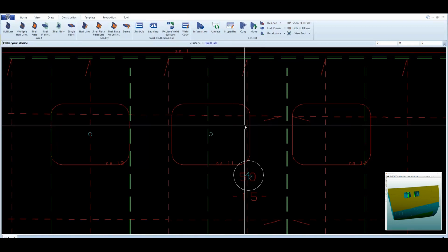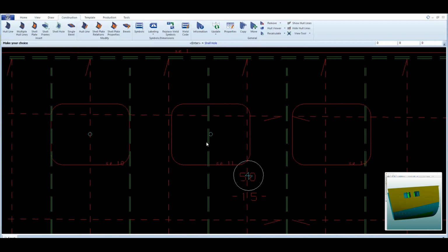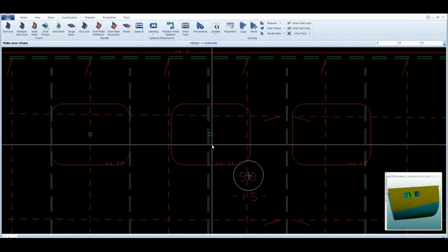If you remember, for the seams that we have created here we used the maximum property. This maximum projection property is a special projection property made with dedication for holes, because as you remember, it is a combination of the inside and outside projection. The inside projection refers to projection on the inner shell plate surface, that is opposite to the shell plate normal, and the outside projection refers to projection on the outer shell plate surface, that is parallel to the shell plate normal. The result is the outer contour of the union.